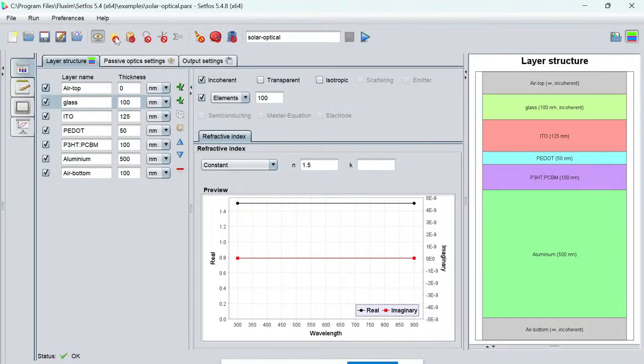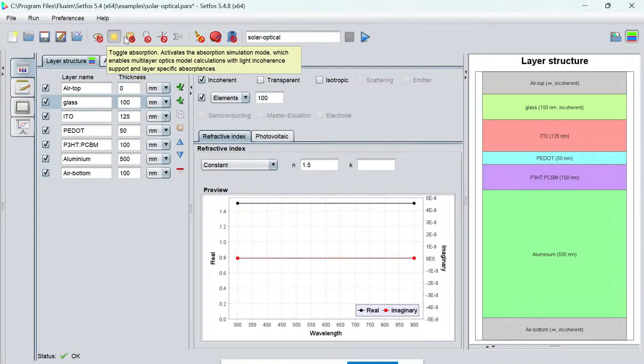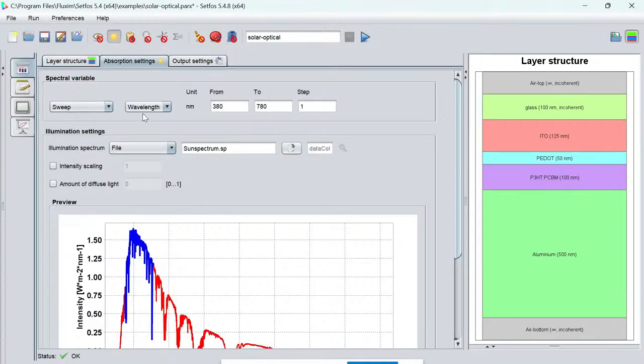And for that I also need to enable the module. As I told you in the presentation, for optical analysis the module needs to be enabled. So I click on this absorption, and the optical absorption module has been updated. This is enabled. These are the top modules: absorption, drift diffusion, emission, and advanced optics scattering. So the absorption module is enabled.